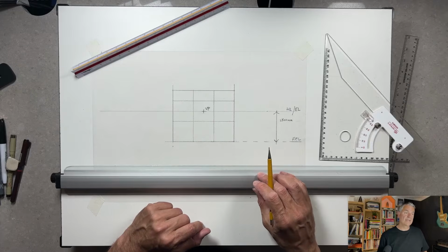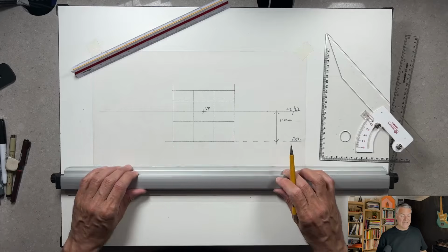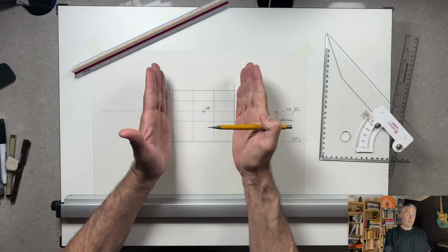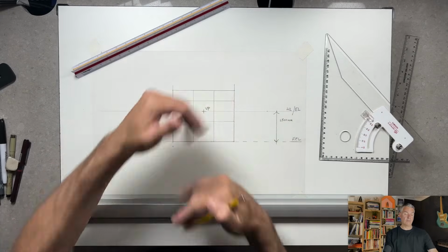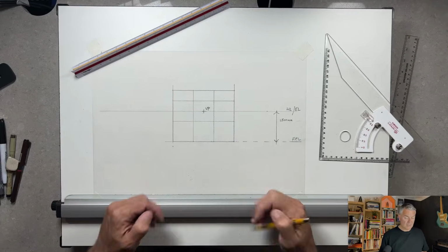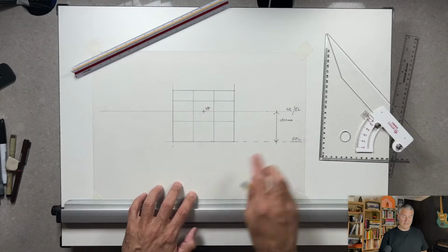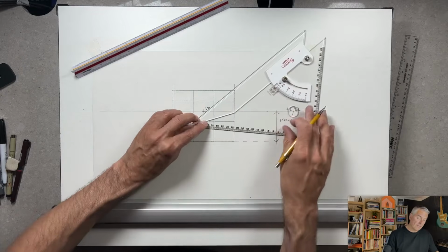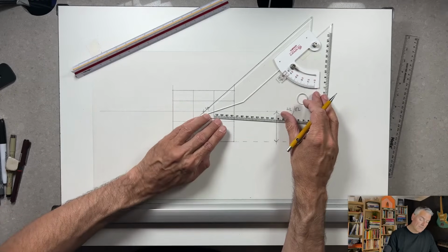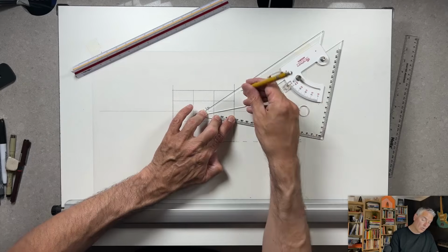The next thing we need to do, now that we've got our vanishing point in and our two-dimensional back wall, 3 meters by 2.5, is to know our distance out into the space. The first thing to do from our vanishing point is to draw 4 lines from the corners of our back wall.